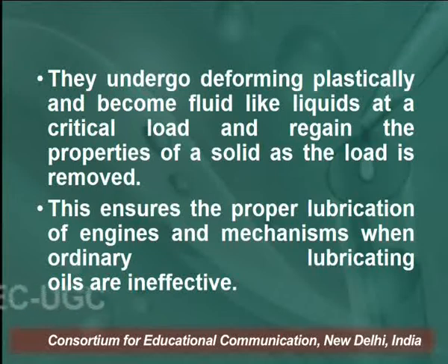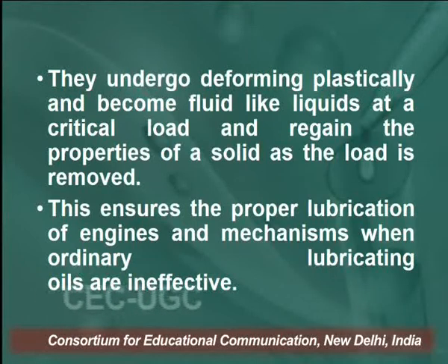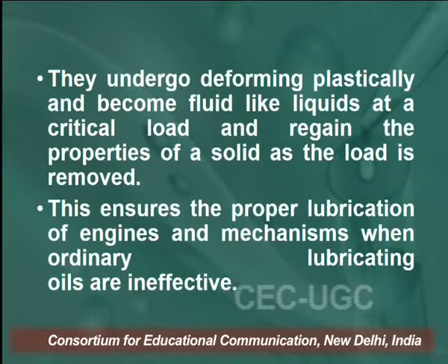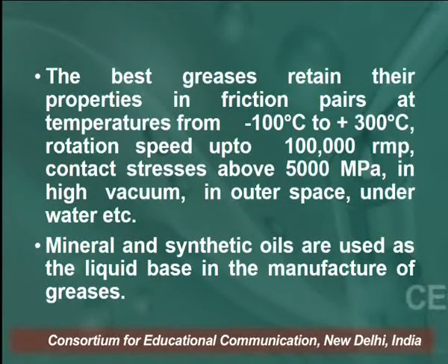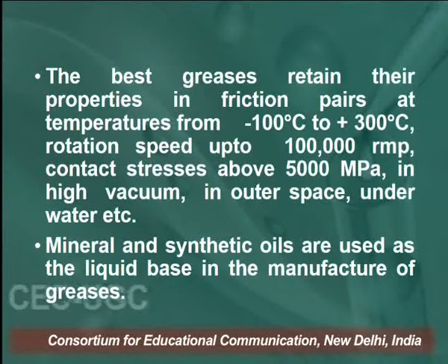This ensures proper lubrication of engines and mechanisms when ordinary lubricating oils are ineffective. So in this way, greases have an advantage over the lubricating oils. The best greases retain their properties in friction pairs at temperatures from minus 100 degrees centigrade to plus 300 degrees centigrade, rotation speed up to 100,000 RPM, contact stresses about 5,000 MPa, in high vacuum, in outer space, underwater, etc.